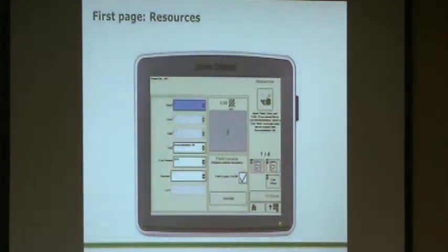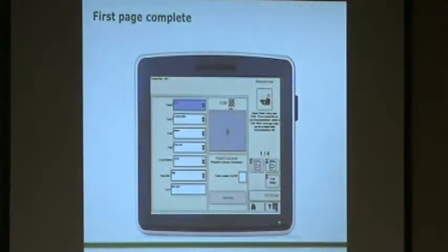One thing that a lot of people will miss and we get a lot of calls on is people won't put in the task here. Okay, they'll leave it as documentation off. In order for the page to paint for you to start recording, you have to have a task in here. Harvest. If you don't click that on, it won't work. So here we've got client, farm, field, task for harvest, crop season, operator. You can put that in if you want.